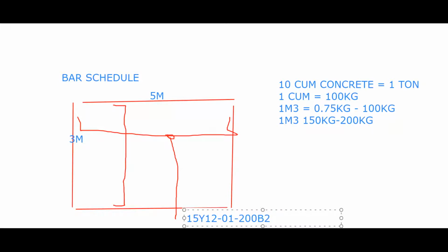Okay, then he will now label this one. Remember, this is the difficult method of getting this thing. But I can tell you, if you use the nominal method with experience, somebody will spend 1 week doing this thing. You, as an experienced engineer, get your value by just getting the volume of your concrete and applying the nominal reinforcement.